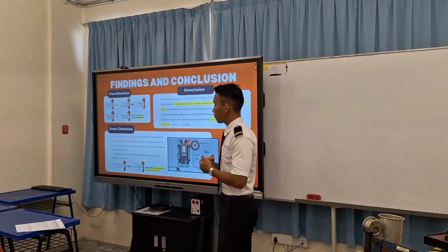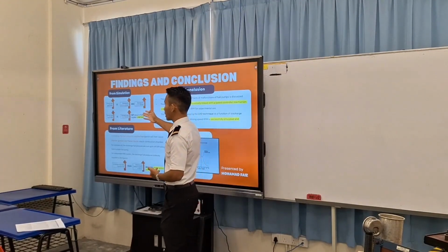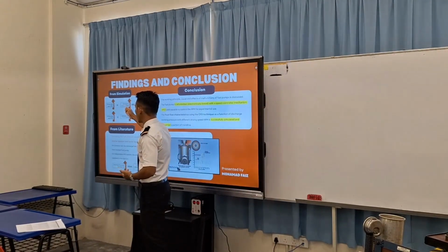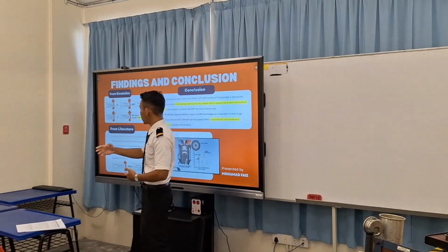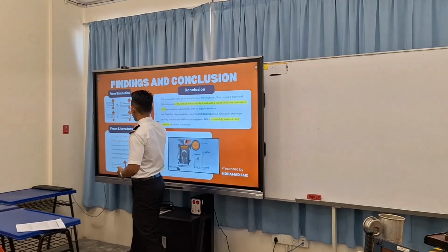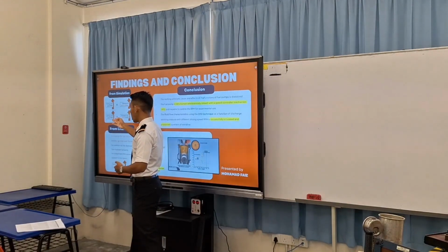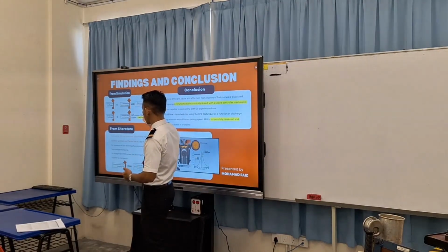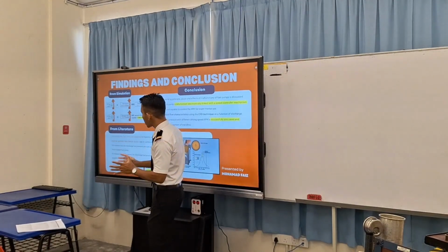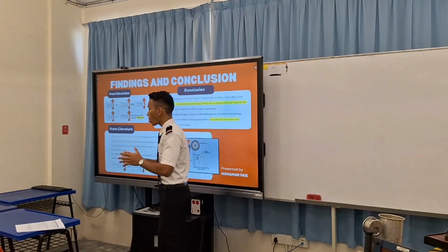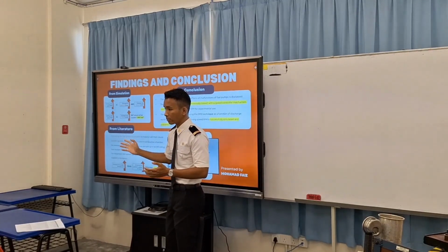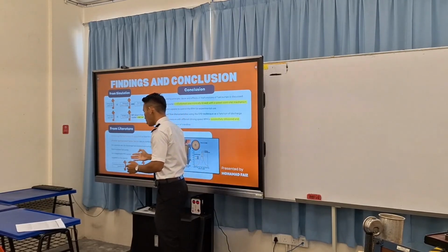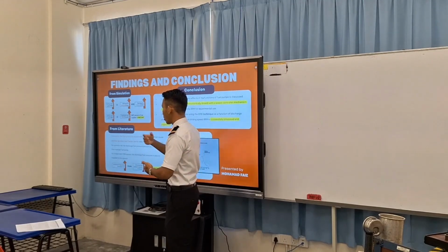First, conclusions from my findings, from the simulations, we can see this graphic right here. The driving shaft RPM is proportional to the pressure and velocity, whereby increasing the RPM causes the pressure to increase and the velocity to increase. The same goes for the flow rates, increasing the driving shaft RPM increases the flow rate, but the amount of supply is constant. But we know that again, this simulation is only for the MOHAMMAD system, which is the direct line, so from the fuel pumps it goes into the injector directly, and not for the conventional system, which has a lot more considerations in the system.